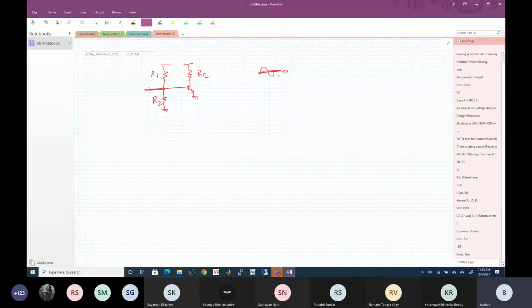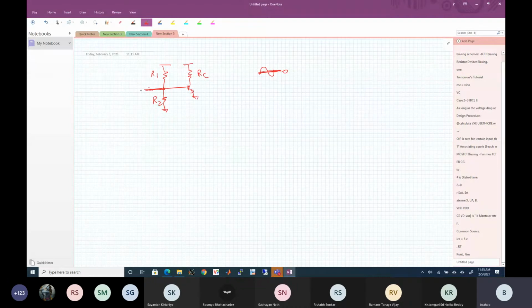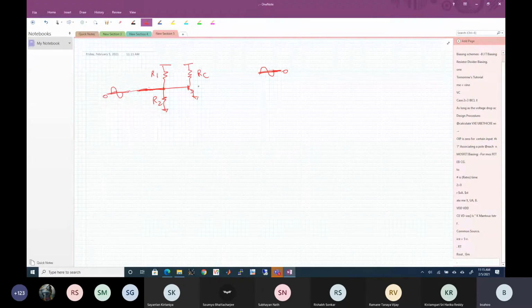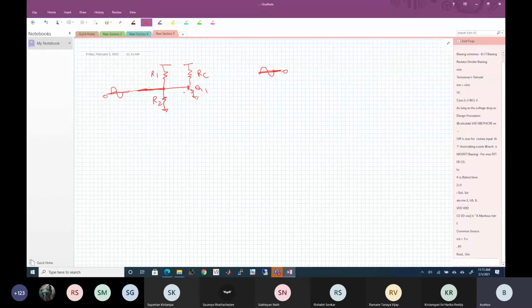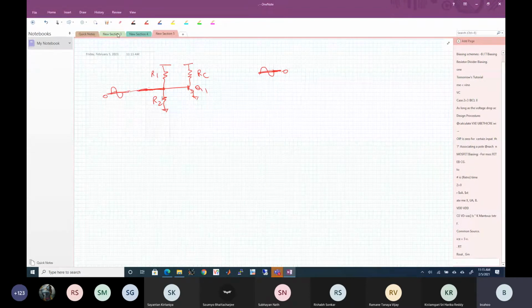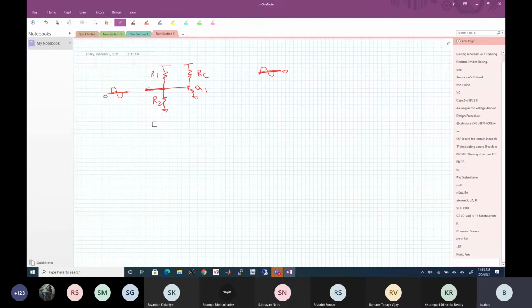So the microphone generates a signal. Now if I connect that signal generator directly here, the signal will be swinging around 0 volts, which means my transistor is not biased. So I should make sure that I couple the signal without disturbing the bias point of the circuit. What you would do in that scenario is use a capacitor, which is going to give you a DC level shift. Okay, so Vin is here, this is Vx.